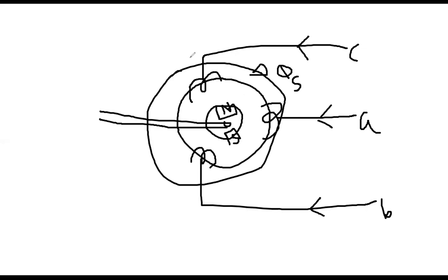But what will happen? Everybody follow me, because initially that rotating magnetic field phi s is being developed. What is the meaning of that? This means North Pole and South Pole are inherently being created, because the field is moving. Initially, this North Pole and South Pole are fixed because the motor has not started rotating. It is static, so these physical poles are not moving. But the internally, inherently generated North Pole and South Pole are moving. So when the externally generated pole is aligned with the North Pole, what will happen? North will repel North. Because the field is moving in this direction, this North Pole will try to move in this direction.